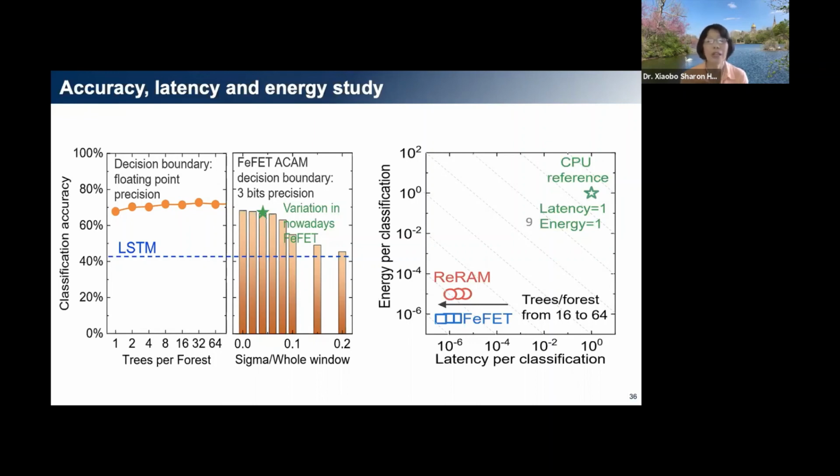Now, talking about different technology choices, MTJs, especially these SOT MTJs, these are new magnetic memories using the tunnel junction. They can have much lower write voltage, and as MTJ-based CAMs, which we are also working on with a couple of groups working on these devices, they can be a nice device choice for this type of application, where you need lots of write, but you also want some non-volatility. Then MTJ type of device could be a better choice.